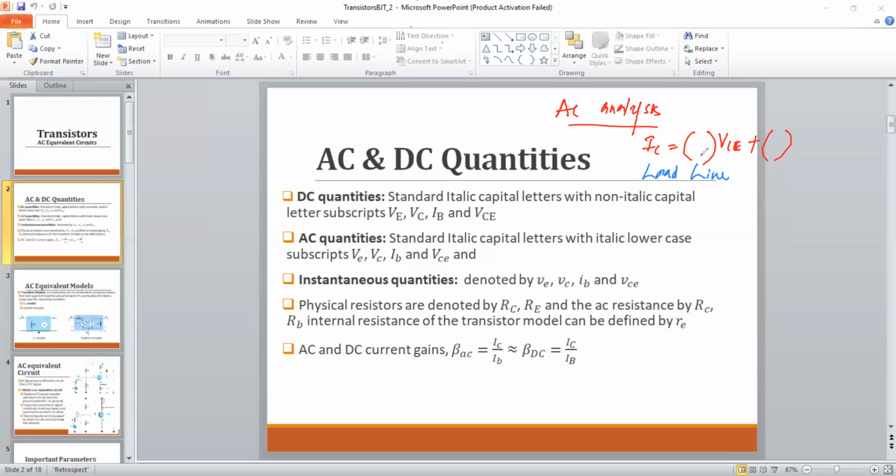Once you plug in those values and implement the circuit, if it exactly matches the analytical values, you will place the Q point of the transistor as planned. If that is not the case, because we need to align with practical values we can get from the market, the Q point of the transistor would vary accordingly along the DC load line. So we can come closer to the real requirement by doing this mathematical calculation, and from that point onward, you can use a trial and error approach to get the exact Q point and resistors.